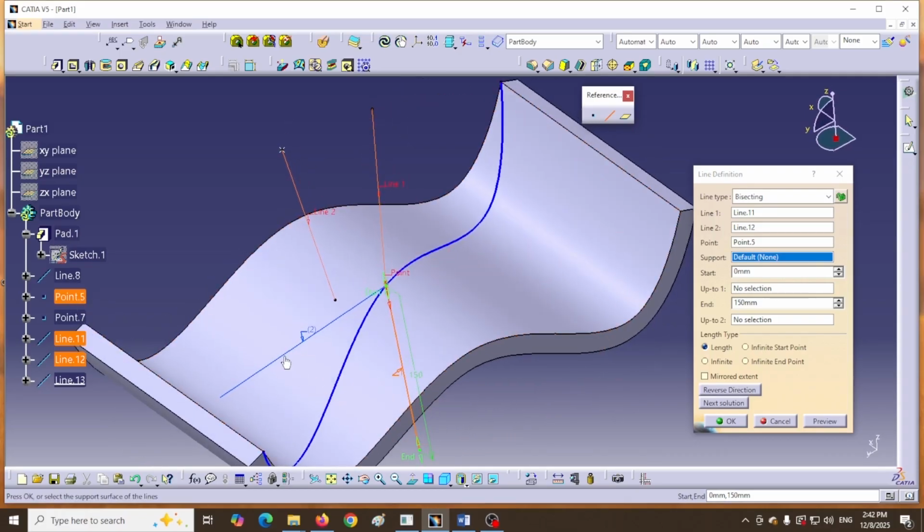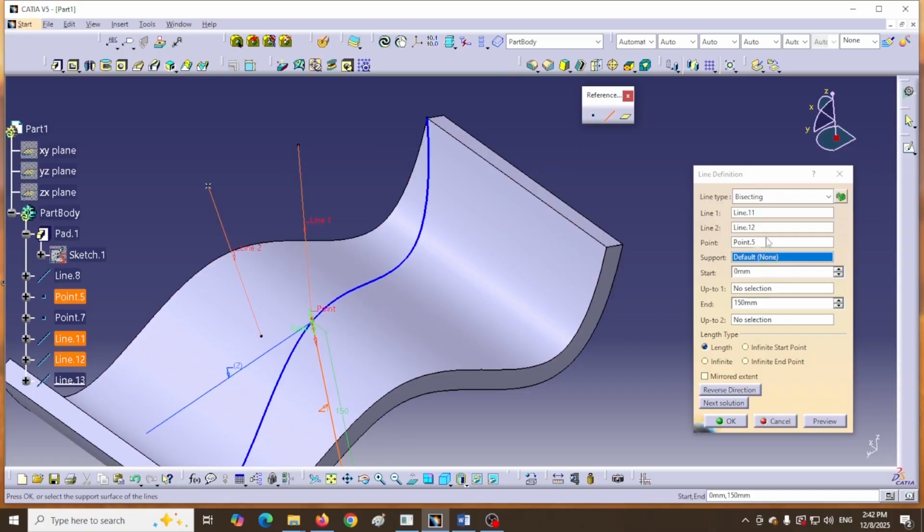So, if you want to create a bisector between two skew lines, you must also define a reference point to specify the plane for the solution. This point can be anywhere, on one of the disjoint lines or a point at one of the corners of the figure.